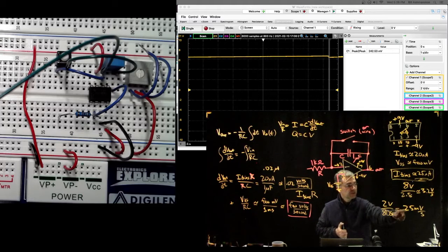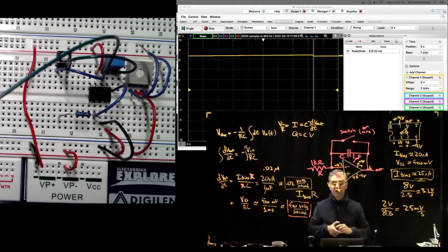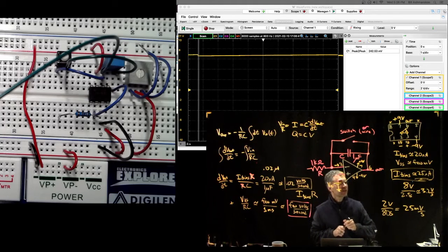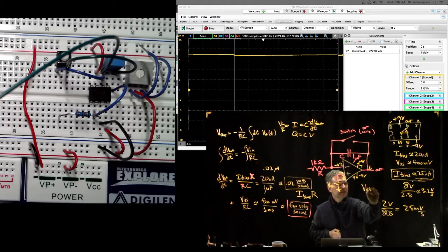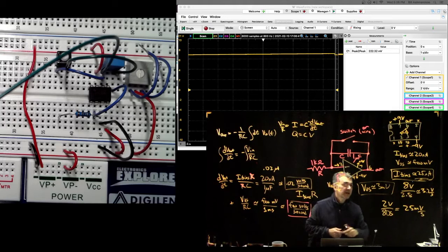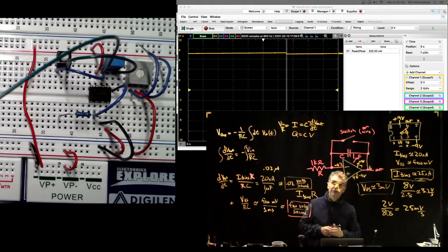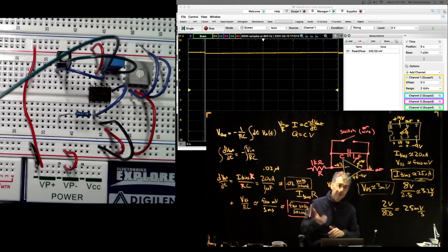And then also you say, well, 25 millivolts per second is so much smaller. It's about 1% roughly. I mean, it's 2 orders of magnitude smaller than 3.2 volts per second. So I guess that tells us that indeed V offset is about 3 millivolts. Okay, so we think we've determined Ibias about 25 nanoamps and V offset about 3 millivolts by looking at this opamp integrator. So it's kind of fun to extract those numbers that way. And you can see the math on page 6.